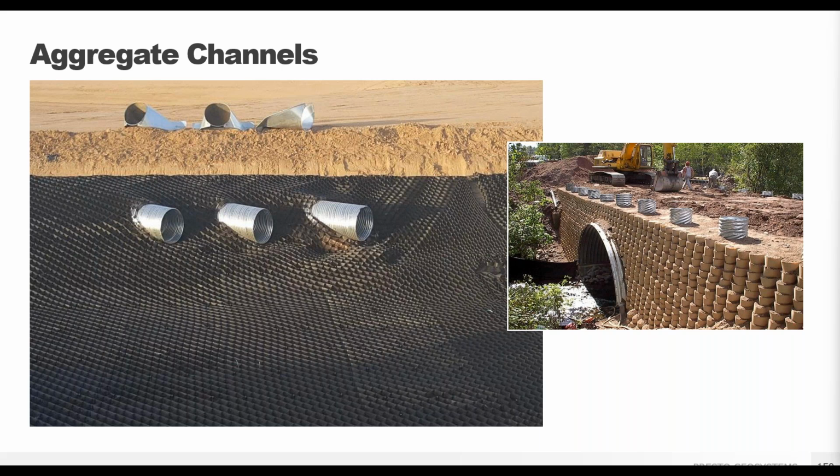Here we see some drainage pipes from a nearby detention pond, and it's very simple to complete field cuts of the GeoWeb panels and accommodate structures like these, so there are no areas left unprotected. That area right below the drainage weirs should be built more robustly, since this is the area with the highest potential for stone washout due to the turbulence of water coming out of the pipes.